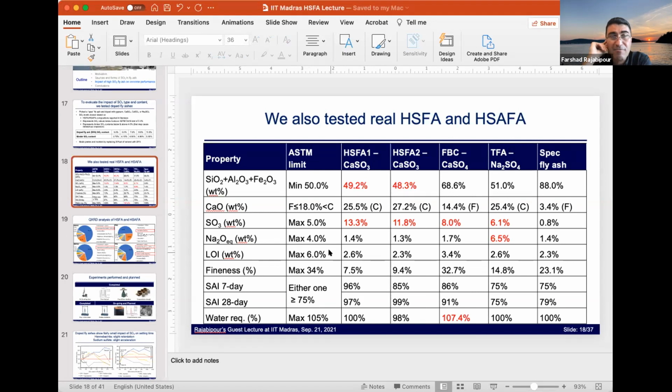But otherwise, if the question is more general, ultra fine fly ash, of course, tends to be more reactive than regular fly ash, and more effective in providing pozzolanic properties, ASR mitigation, et cetera, assuming that it has the right composition and fits the specification limits for the most part in terms of the alkali and LOI and things like that.